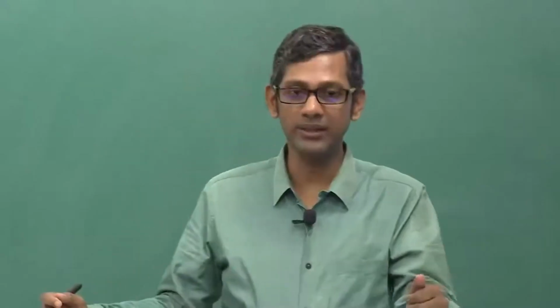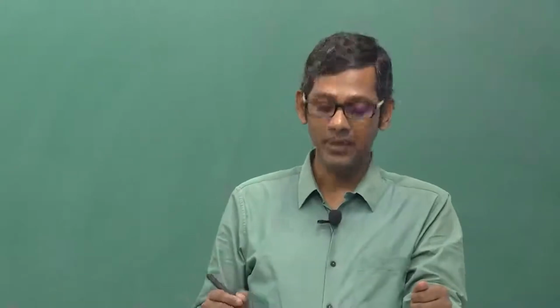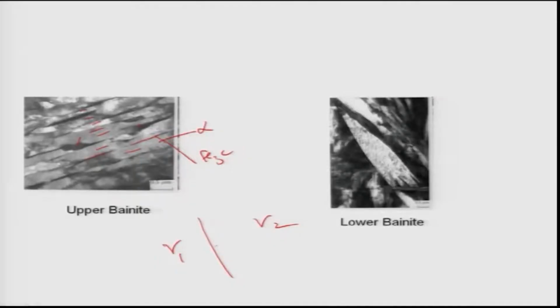So that means, if I have to draw the microstructure, suppose I have gamma 1 and gamma 2 grains, and this is a grain boundary. What will happen? We have quenched the steel to a temperature of about 400 Celsius. So at the grain boundaries of gamma, alpha plates or alpha needles will shoot out, like I have shown you just now for proeutectoid alpha, and they will grow very fast.